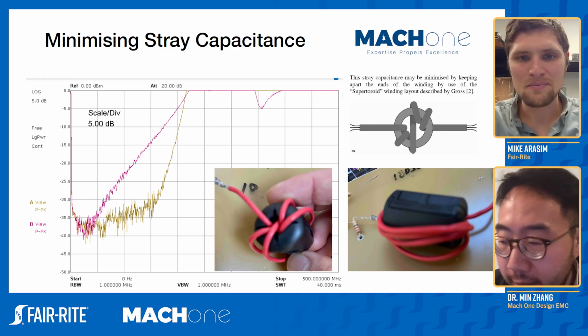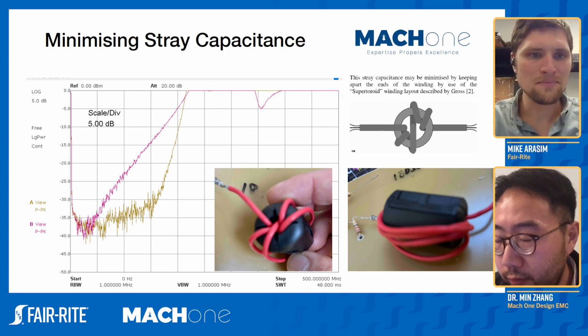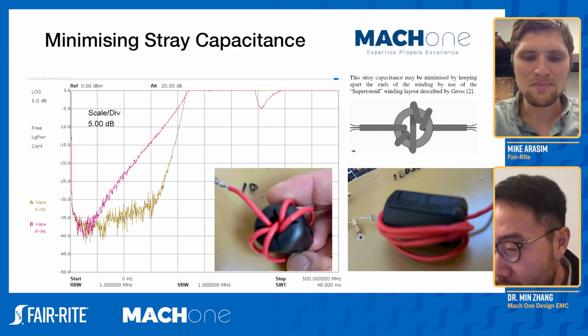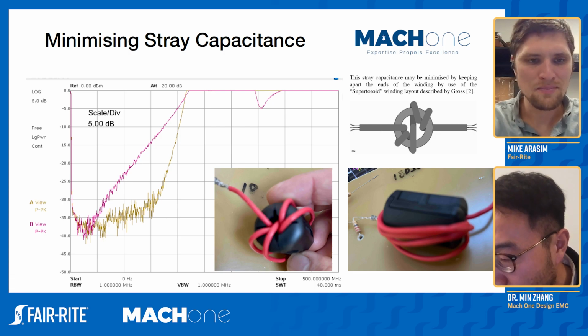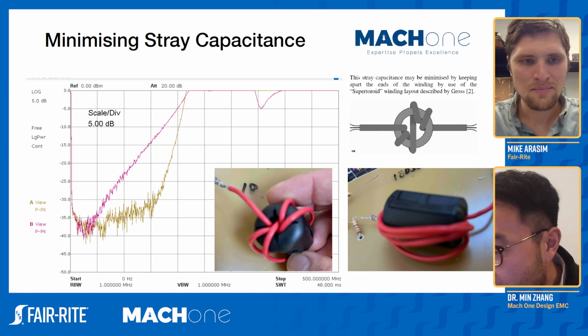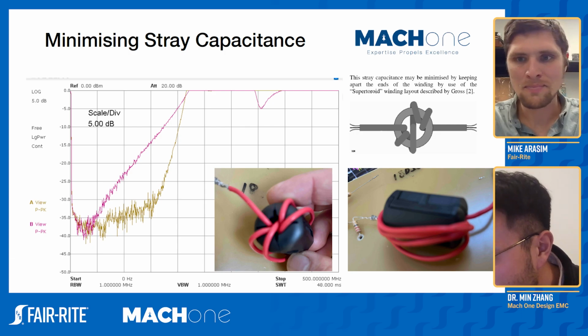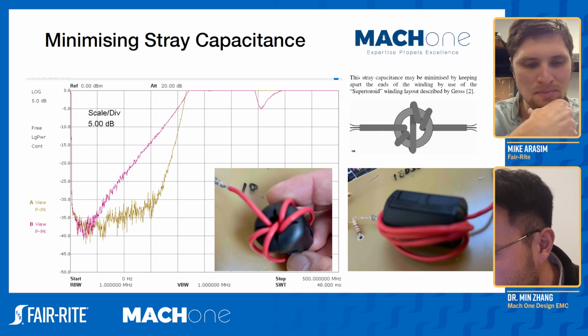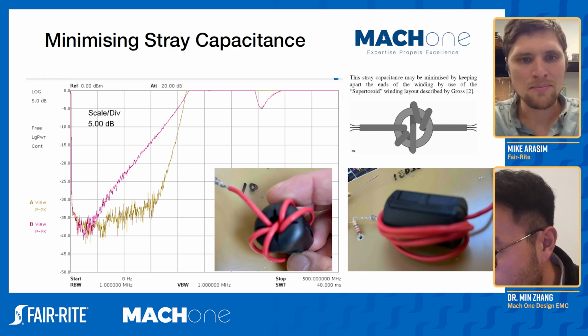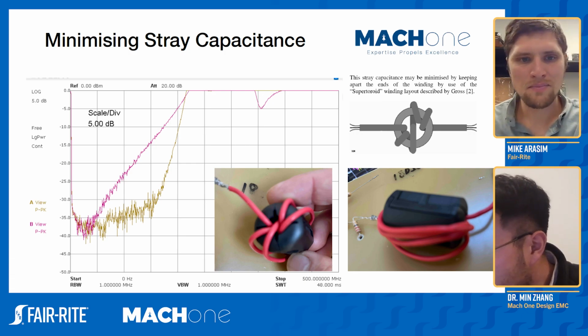So that's definitely a significant increase in terms of the insertion loss. However, one thing we noticed is that it's definitely shifting to a lower frequency point, as you mentioned. And also we notice this very sharp drop, as you said, here as well. So it's quite peaky, as you said. And the reason is because of the parasitic capacitance as you introduce more turns.